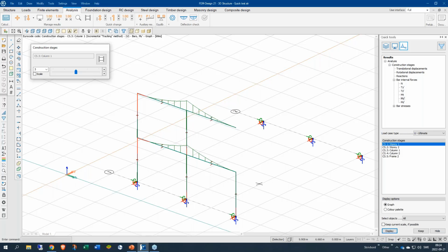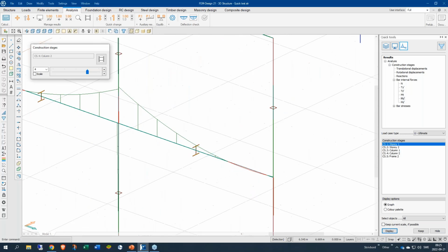in this part, it will just be placed under the beam. There will be no change in the moment distribution because this beam and this structure already has its load taken down in a certain way. So in this case, the column is just placed under the beam. And for the next state, there will be the next column, but here I've added the live loads as well.